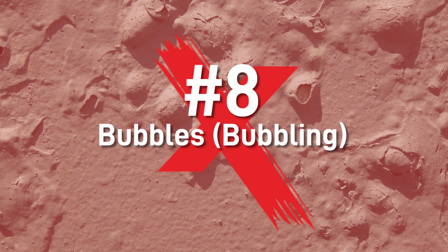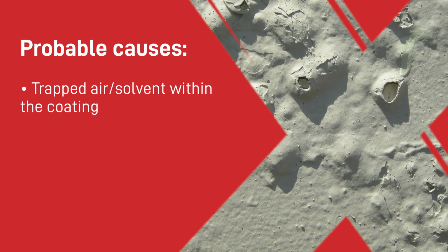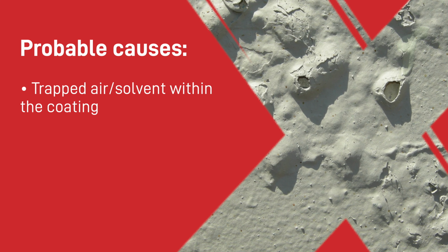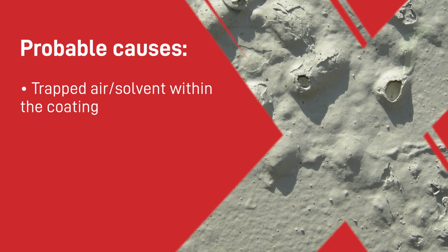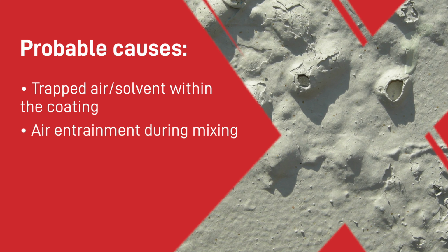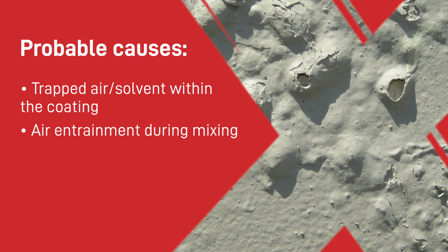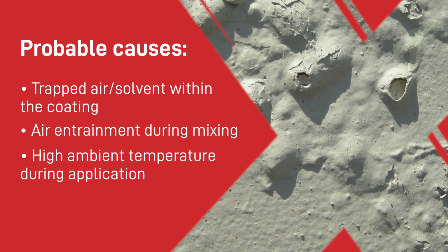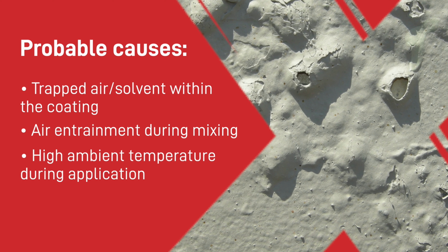Failure number 8 is bubbles or bubbling. A probable cause of this is trapped air or solvent within the coating that is not released before the surface dries. Air could have become entrapped during the mixing phase, or a high ambient temperature during application can also cause significant bubbling.